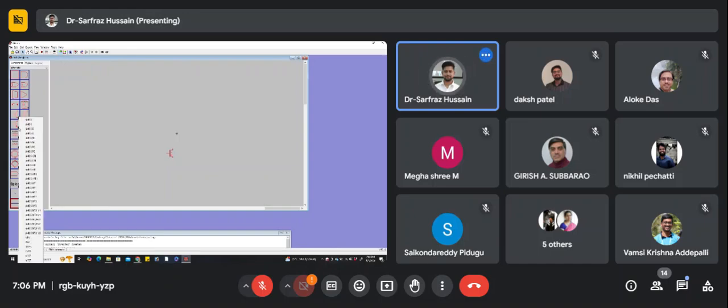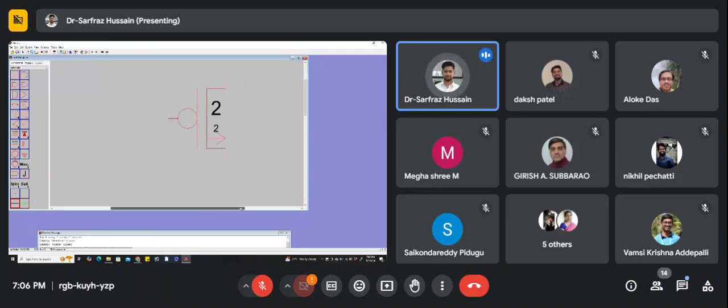So I place the NMOS below, and I'll place the PMOS at the top. Once you place this, there is one more thing to remember. Let me zoom in. Here you can see the PMOS. Here we have four terminals. The terminal shown here with this arrow mark is nothing but the bulk. Near to the bulk is always the source. So this becomes the source, this is the bulk, this one is the drain, and this one is the gate. We need to remember this, because whenever we are designing, we need to focus on this.